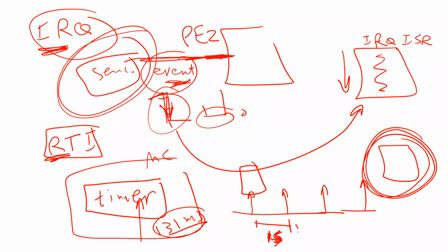If you make an interrupt every 1 second, I'm sure the subroutine is going to be executed every 1 second, and then I can write here: flip LED. Very easy, right? So every 1 second I call the subroutine, and it flips the LED. This way you can make a flashing LED. So if you need periodic interrupts, you have to use RTI.